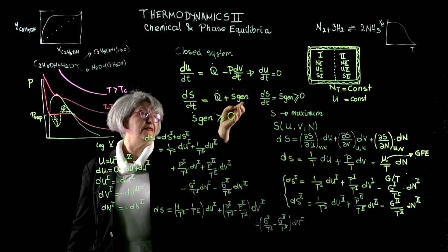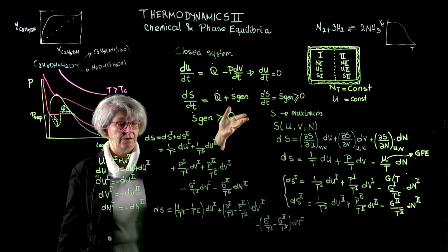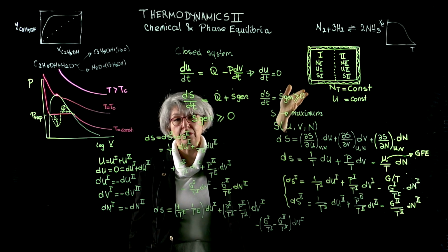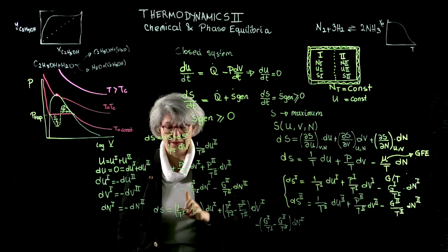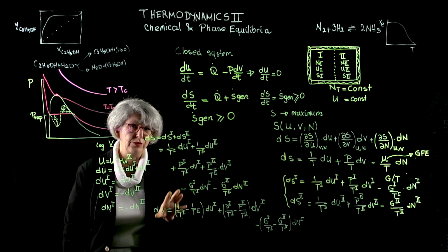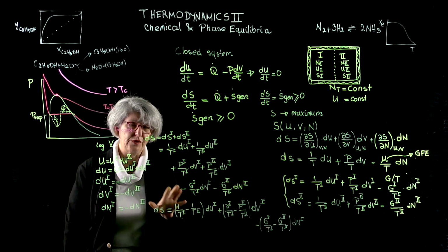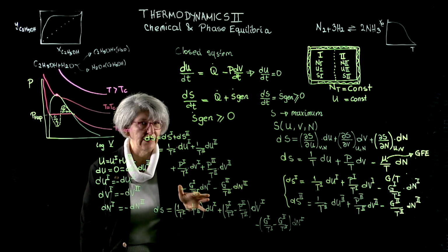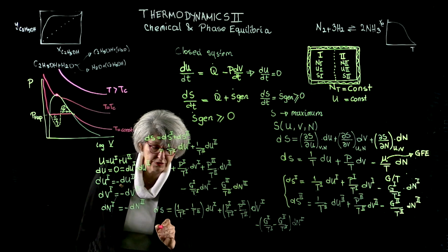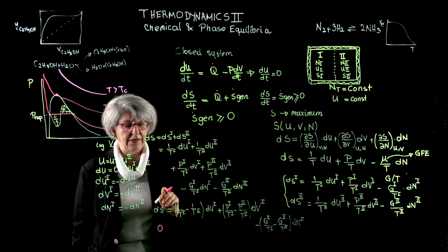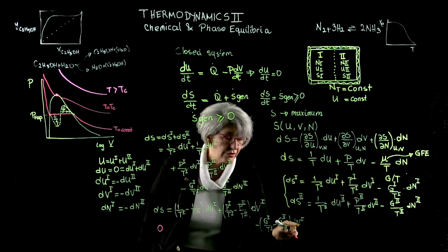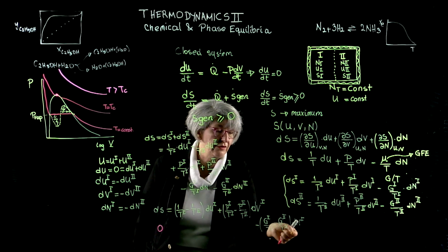Now, at the point of equilibrium, entropy generation is greater than or equal to 0. So we're going to take the entropy generation to be equal to 0 at the point of equilibrium. All right? Point of equilibrium is point of stagnation, no entropy generation. So dS is equal to 0. If dS is going to be equal to 0, either these terms or their multipliers should be equal to 0.